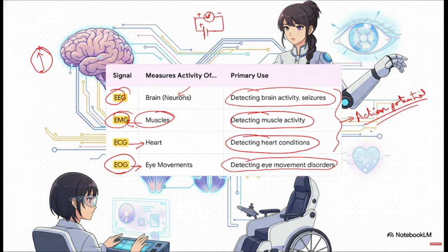The red one is to be put into the positive terminal, and the black one into the negative terminal. Under that condition, I will be getting a positive voltage reading. What if I change the terminals, that means I put the red terminal to the negative and the black terminal to the positive end? I'll be getting the same voltage, but the sign of the voltage will change. It will be a negative voltage reading.